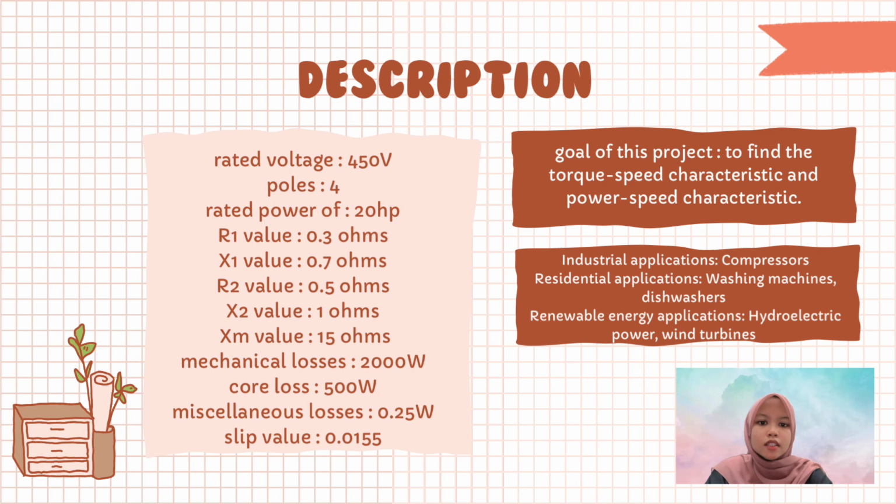The magnetizing reactance is 15 ohms. The mechanical losses are 2000 watts. The core losses are 500 watts. The miscellaneous losses are 0.25 watts. And the last one is the slip value, which is 0.1555. This three-phase induction motor has a relatively low stator and rotor resistance, indicating low losses and high efficiency.